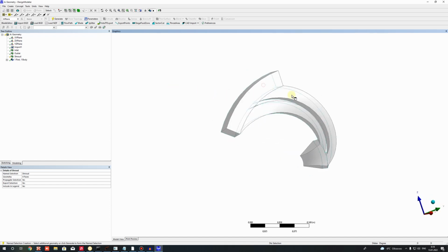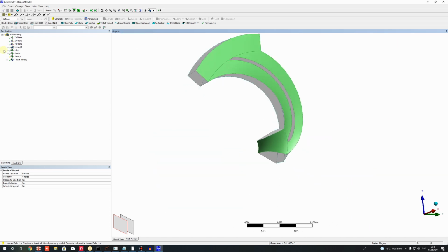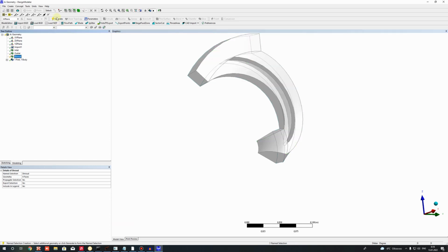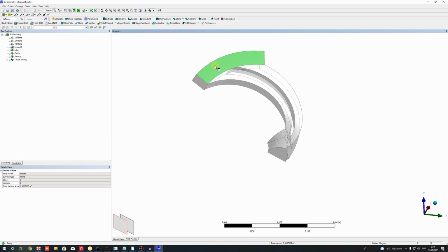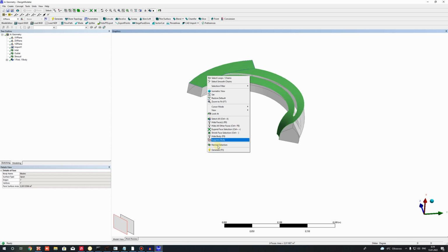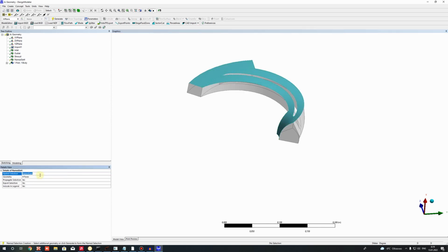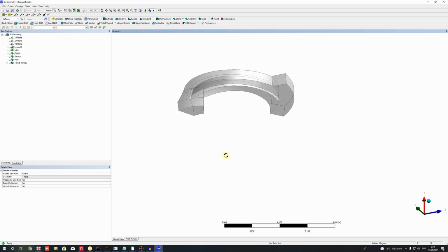So the next step, let's choose the hub, create, just click generate. We didn't click it in the previous steps, so now let's choose the hub surfaces and make the creation of the named selection. Call it hub, we generate, and you will get the hub, shroud, inlet and outlet boundaries, and the remaining surfaces